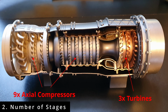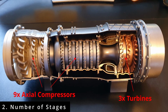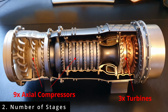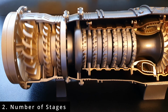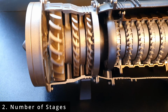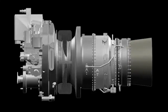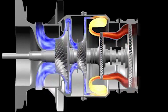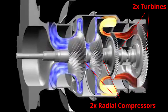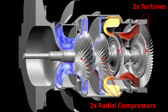Next, we have the option of the number of stages. Stages are the bladed rows of compressors or turbines in the engine. This engine has 9 stages of compressors and 3 turbine stages. The more stages we have, the greater the compression ratio. The greater the compression ratio, the higher the engine's efficiency and the more thrust it produces. However, the more stages we add to an engine, the heavier it gets. There are trade-offs here between weight, efficiency, and cost.